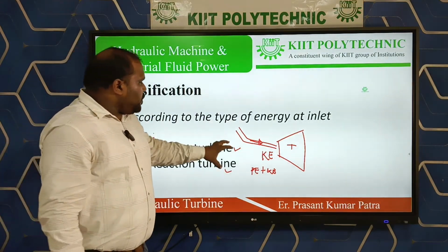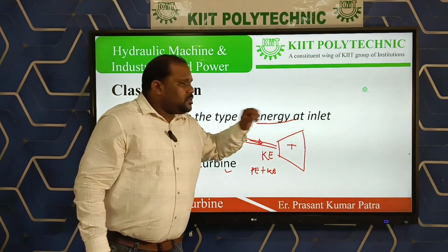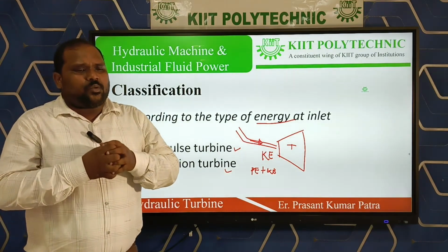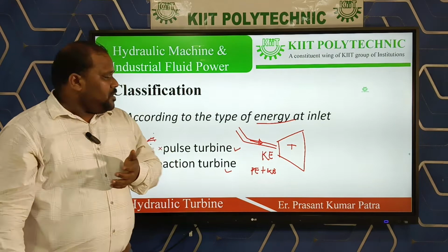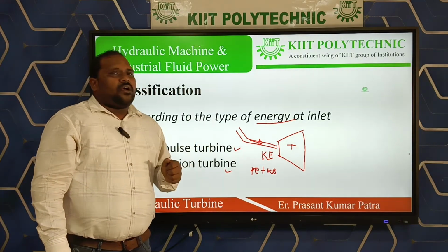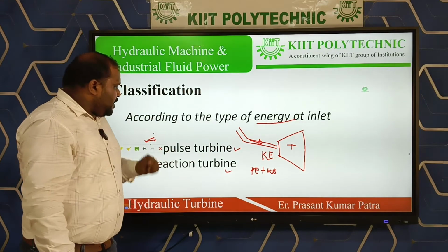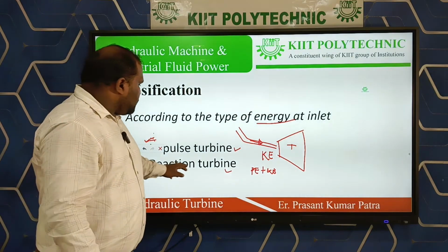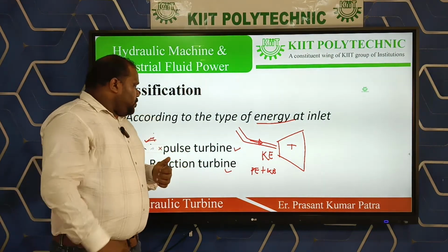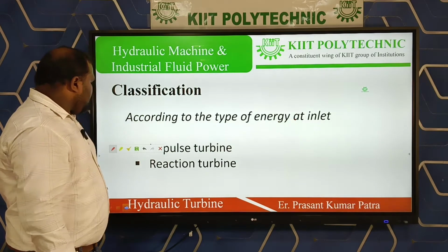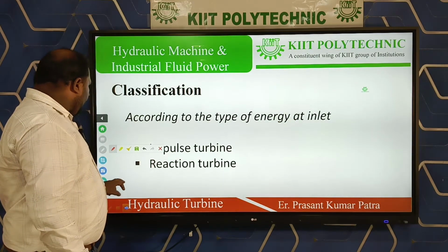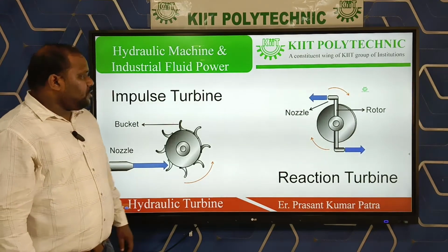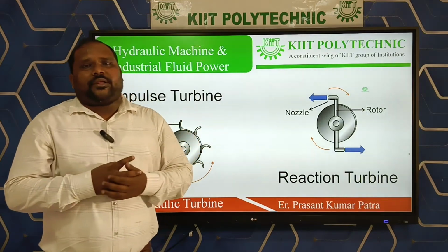So totally it depends upon the energy at the inlet. If the energy present in water is totally converted into kinetic energy, then we consider that an impulse turbine. In the second case, if it is partly pressure energy and partly kinetic energy, then it is considered a reaction turbine. Later we will discuss this briefly. Now we will see what is that impulse turbine and what is that reaction turbine.